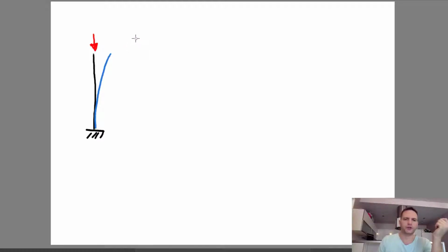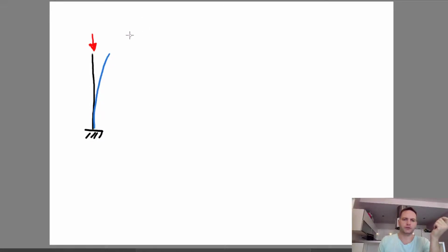And we usually have an equation. You can use finite element analysis, or you can just do some hand analysis depending on what you want to do, where you find out the critical buckling stress is proportional to pi squared times E times I over L squared. And the proportionality here is usually a function of the constraints at both this end and that end. If you don't let this move sideways, if it's pinned, you can get different shapes. It'll buckle out in the middle here instead of just sideways like that.